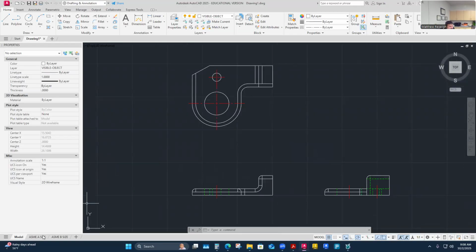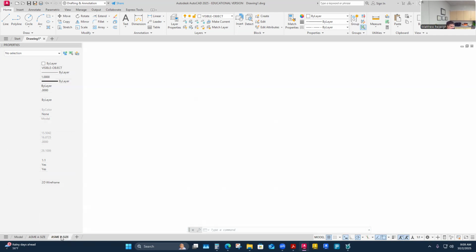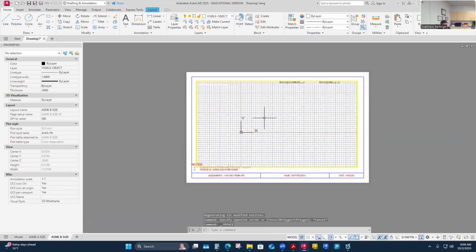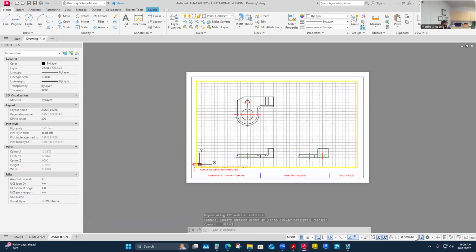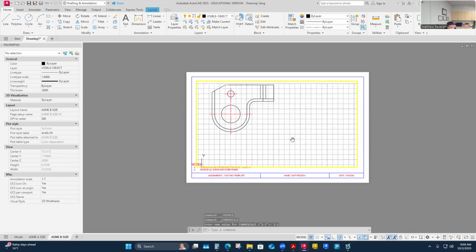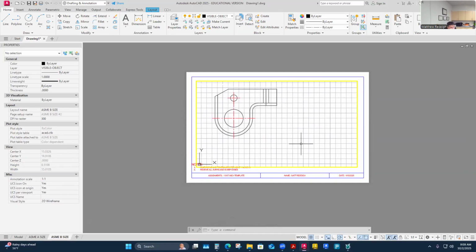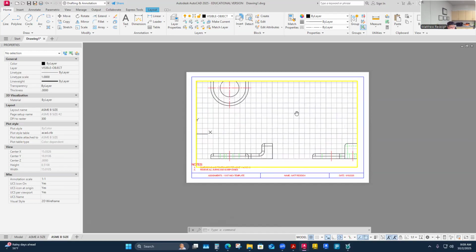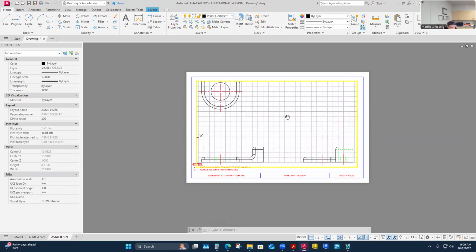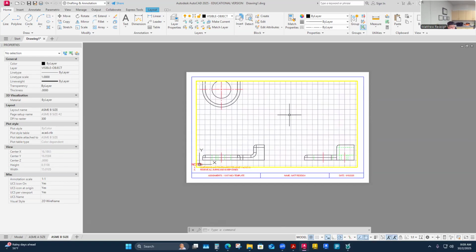Got quite a bit of space here. I haven't looked at how this fits. I have it kind of set as one-to-one, but let me see where I'm at here. Unlock my viewport. This is a B-size sheet. It was one-to-one. Probably the spacing I have is going to be a little bit too big to keep. I'm going to have to do multiple viewports, but I think I'll be able to fit one-to-one on here pretty good with my three views. I'm probably going to take three viewports of this, just by the way I've spaced it away quite a ways. So I might focus this in.